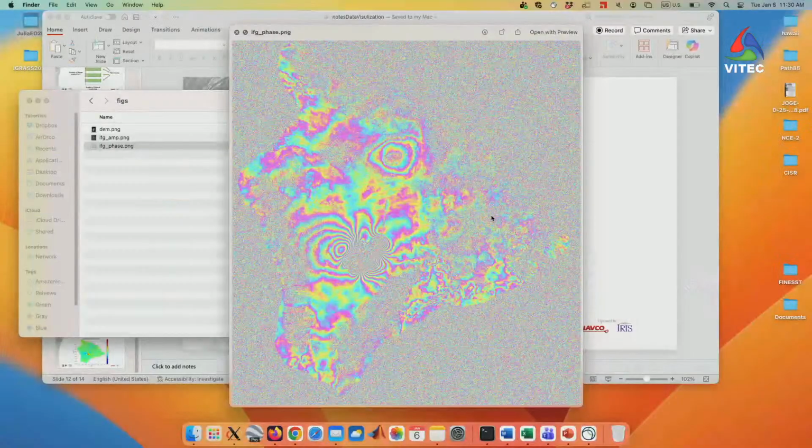But for this deformation, it is too clean and too large, so you're not going to have a mistake whether this is due to the deformation, right? But if you have a small signal, that's what my PhD is doing, there is an 8 millimeter signal right here, and that'd be a big deal. You have to worry about this background noise, because it's going to be smaller than this topography and tropospheric noise. And then what else you see is decorrelation, mostly in the ocean region and any region with vegetation.